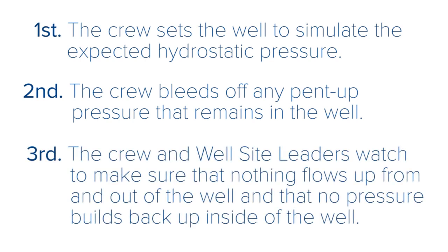Third, the crew and the well site leaders watch to make sure that nothing flows up from and out of the well and that no pressure builds back up inside of the well. The crew made a key error and mistakenly concluded the second negative pressure procedure had confirmed the well's integrity and moved on to the next step in the temporary abandonment.